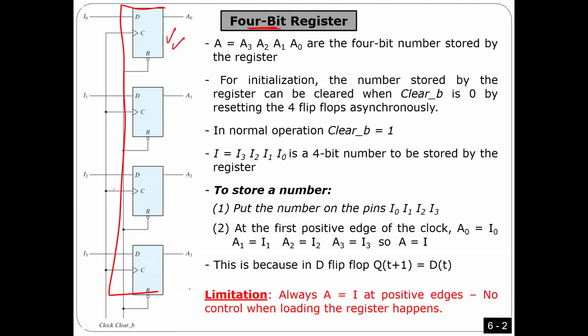And this now becomes like 1 unit. That's why I'm telling you, you need to be very careful here. Yes, I'm using 4 flip-flops, but it doesn't mean I'm going to read individual bits. No, it's one number stored in 4 flip-flops, but I deal with this number as 1 unit. Yes, internally they are stored in individual flip-flops, but I can't manipulate only one of them without changing the others. So I write all of them or read all of them. Any questions about the register?